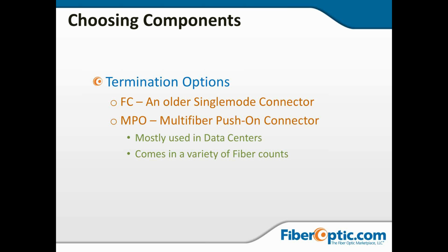We had some stuff in Barbados where we would plug an MPO on one side that would catch all 12 fibers, and then we could run those to individual receivers or individual transmitters, and obviously with the transmitters it would all be on a combiner. All of this running into the 12 fibers in a combiner, and then with the other end we would be receiving 12, sending it to receivers.